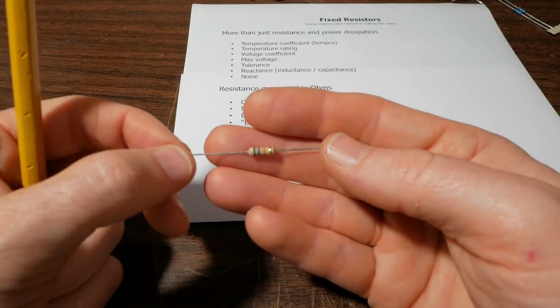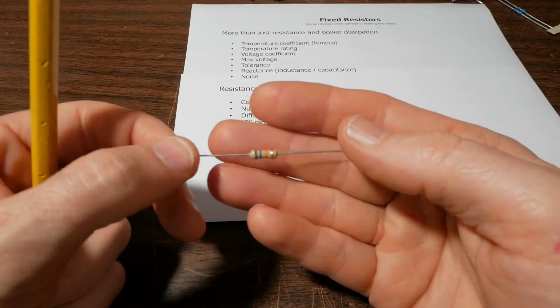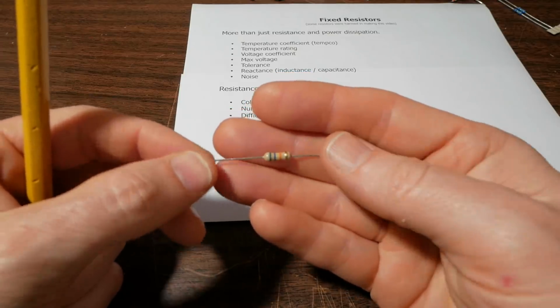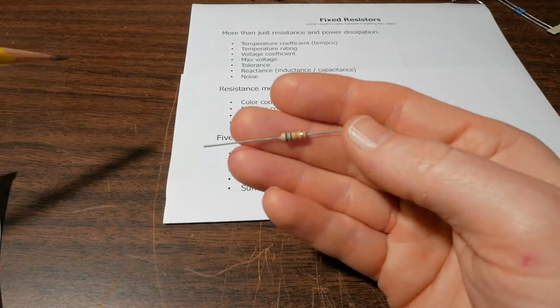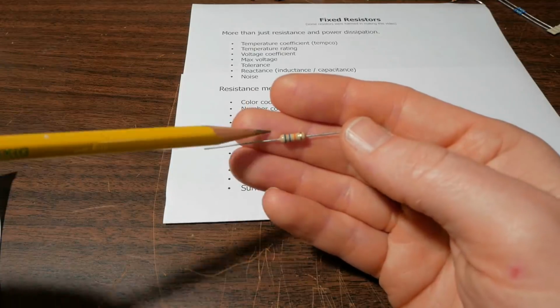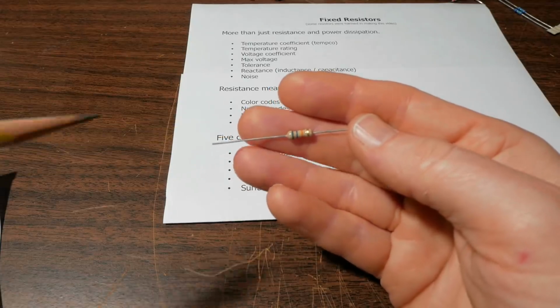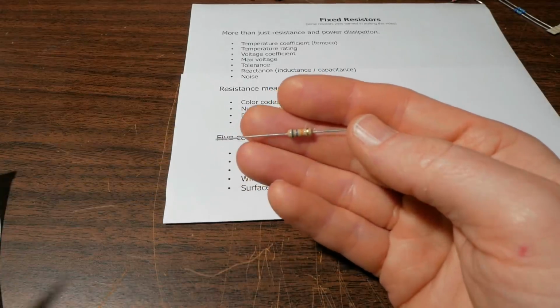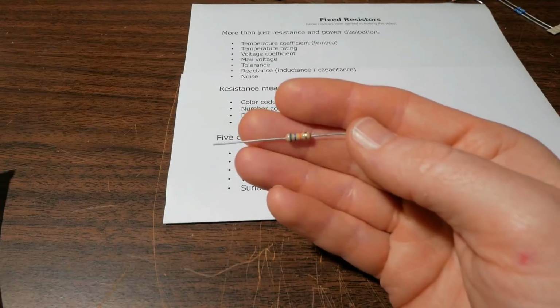The carbon film resistors tend to be better than carbon comp resistors. You can get higher precision with them. They can drift, but they tend to be more stable. But because of the spiral, it does act as a coil, which can be a problem with RF. But usually, the inductance that creates is very low.